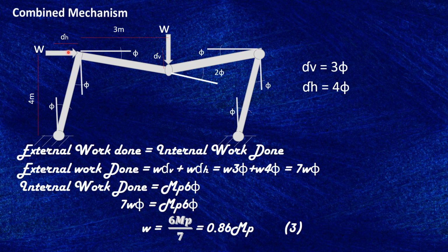We are assuming this joint stays 90 degrees. If we lift this load, it would go back to its normal position because it has not reached the plastic stage. But because of these 4 plastic hinges, they have gone through the plastic state, which means they are not going to get back to elastic. Once they have passed that limit, the structure will stay deflected.